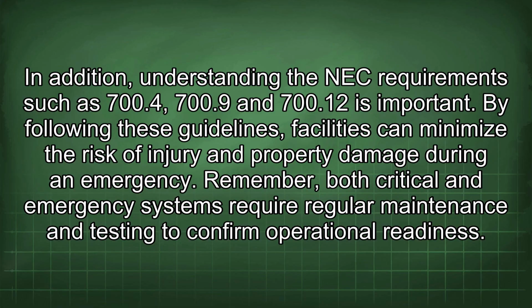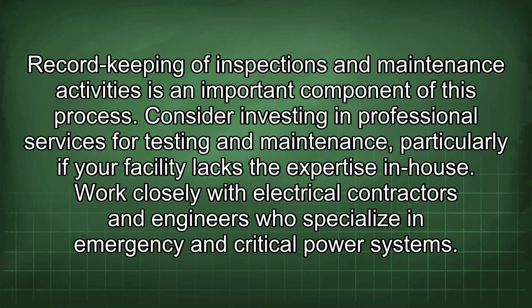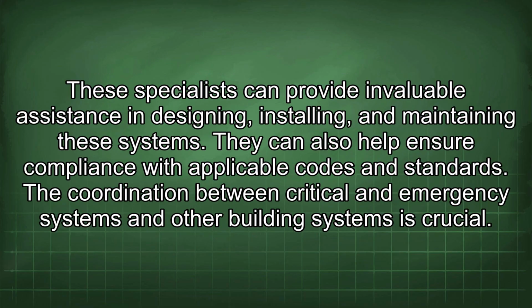Remember, both critical and emergency systems require regular maintenance and testing to confirm operational readiness. Record keeping of inspections and maintenance activities is an important component of this process. Consider investing in professional services for testing and maintenance, particularly if your facility lacks the expertise in-house. Work closely with electrical contractors and engineers who specialize in emergency and critical power systems. These specialists can provide invaluable assistance in designing, installing, and maintaining these systems. They can also help ensure compliance with applicable codes and standards.